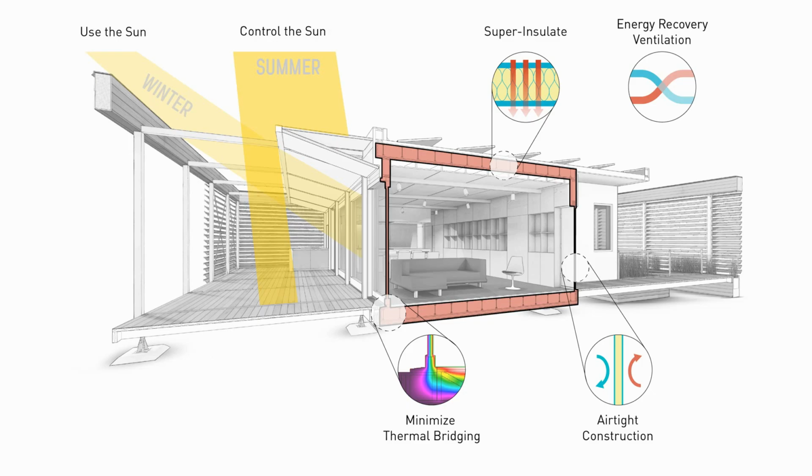And the way to make a very energy efficient envelope is to insulate well above code, focus on things like thermal bridging that the Aqua Tower didn't do, build airtight, and then use something called energy recovery ventilation, which allows you to exchange fresh air from outside with stale indoor air without losing much energy. So the point is, it's a pretty simple set of criteria that have been tried, well established to work, and we know how to do them.